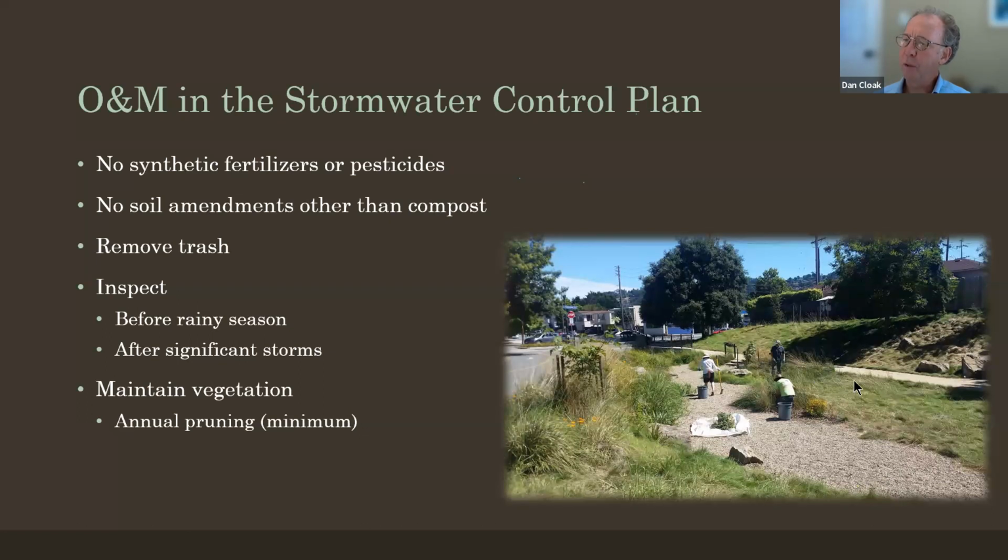Or do you have something that's more like what we were looking at in front of a building, where you would want to make sure that the whole thing is mulched and vegetated because it's much closer to the minimum size and you need that level of performance? We definitely want to encourage the use of active and passive recreation in bioretention facilities.